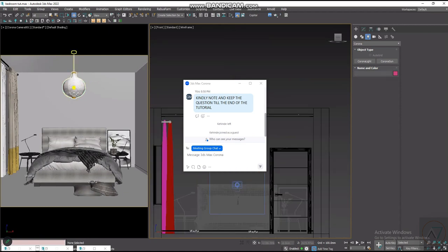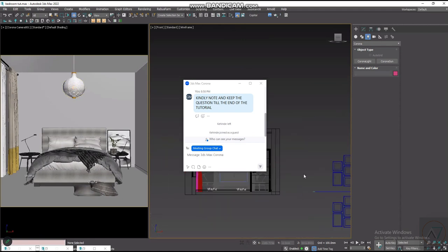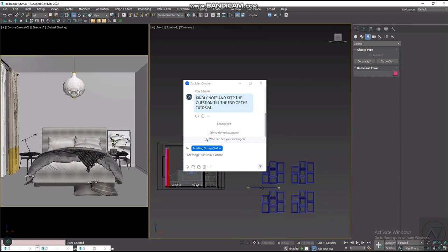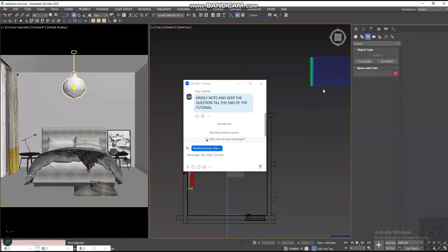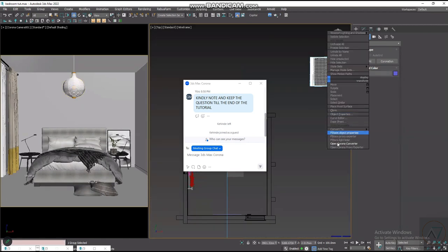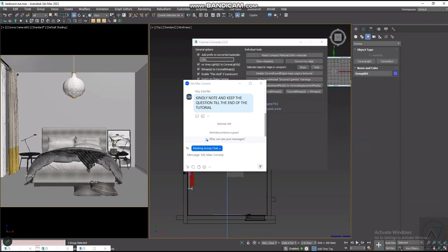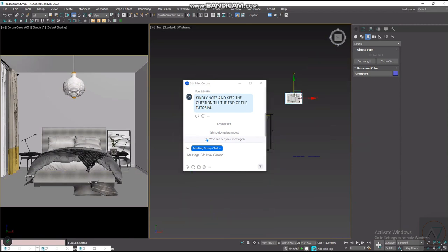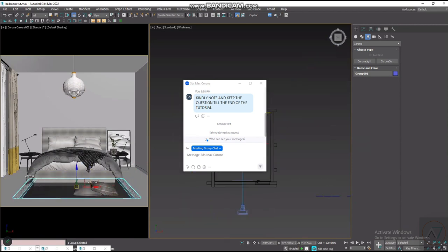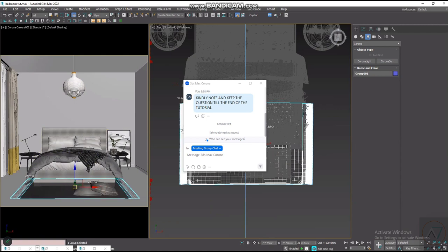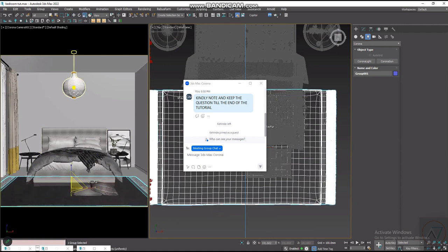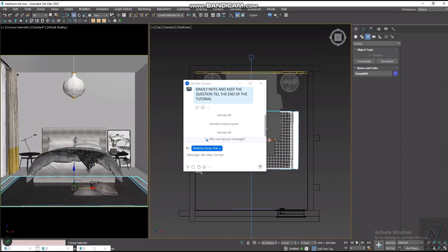So yeah, what else? Once we import the frame here and our carpets, I can just go to top and bring the rug in. The rug too is a V-Ray material. I just convert. Well, I think I've converted it. I don't know. There's nothing wrong with converting it again. Convert. So bring this guy in. It's too small, but you can scale it. Scale. W.